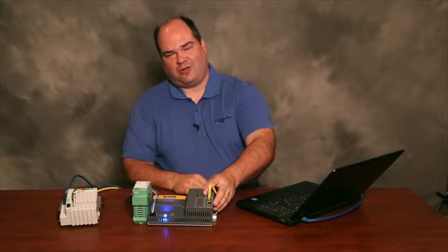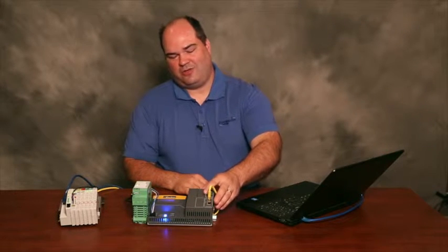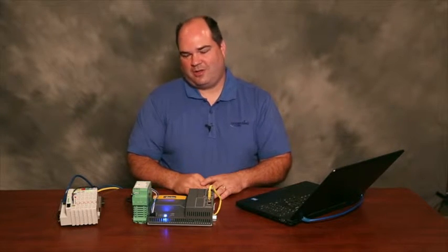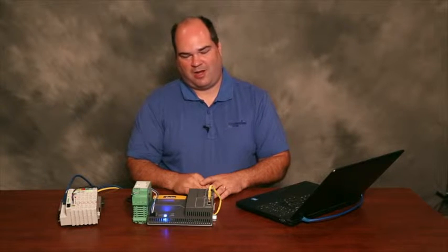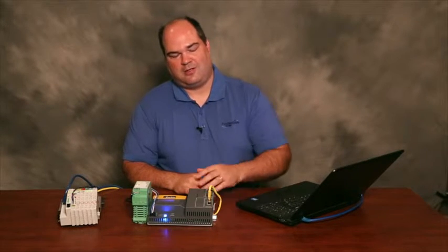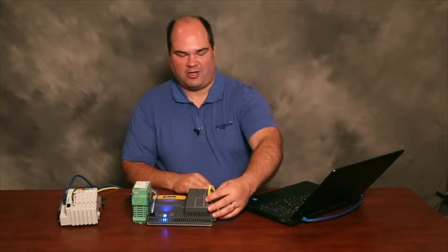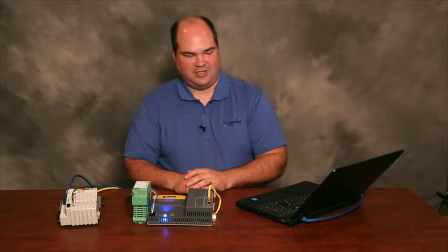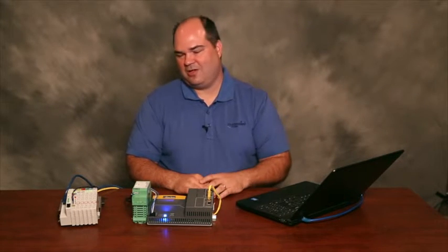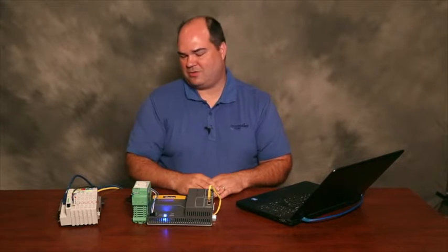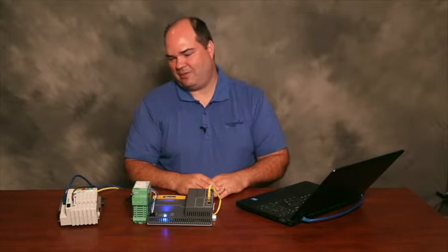Parker's Automation Controller, the PAC, is a new machine automation controller based on the IEC 61131 programming standard with PLCopen motion blocks and the EtherCAT network for high-speed motion and I/O. It also comes with standard Ethernet communications that include TCP/IP to talk to a PC or Modbus TCP to talk to remote I/O, such as WAGO's slice I/O type.